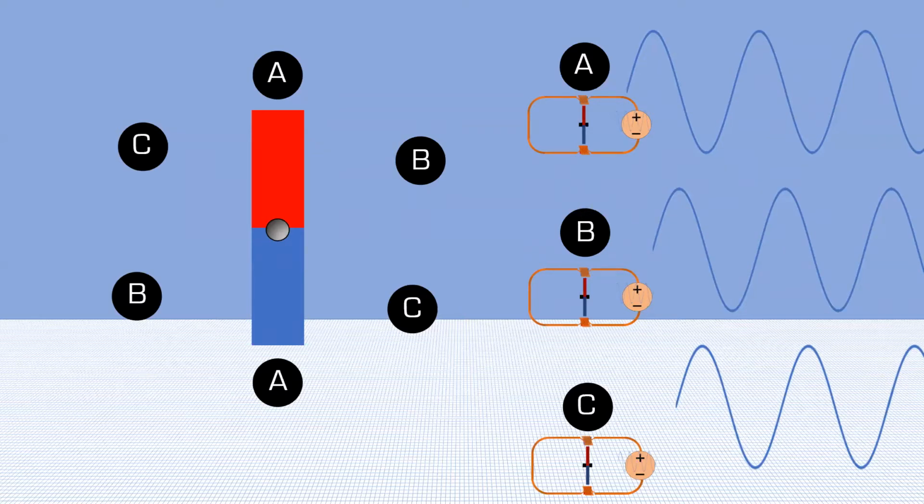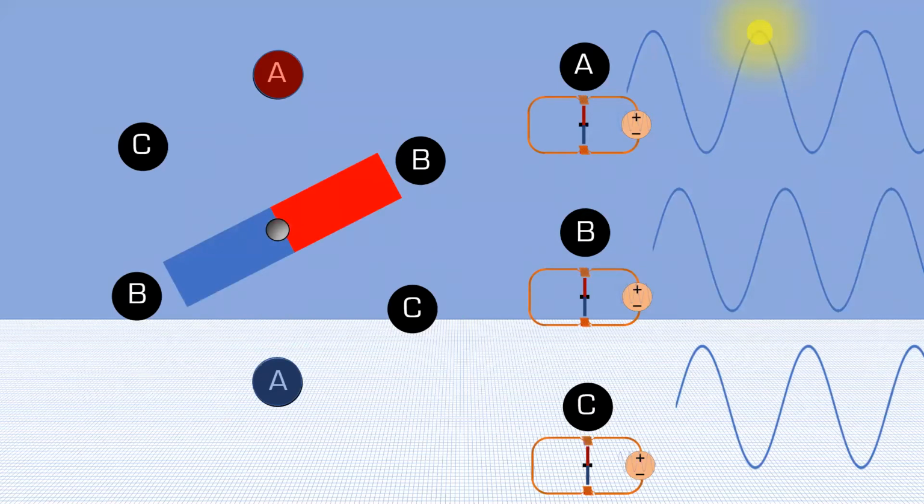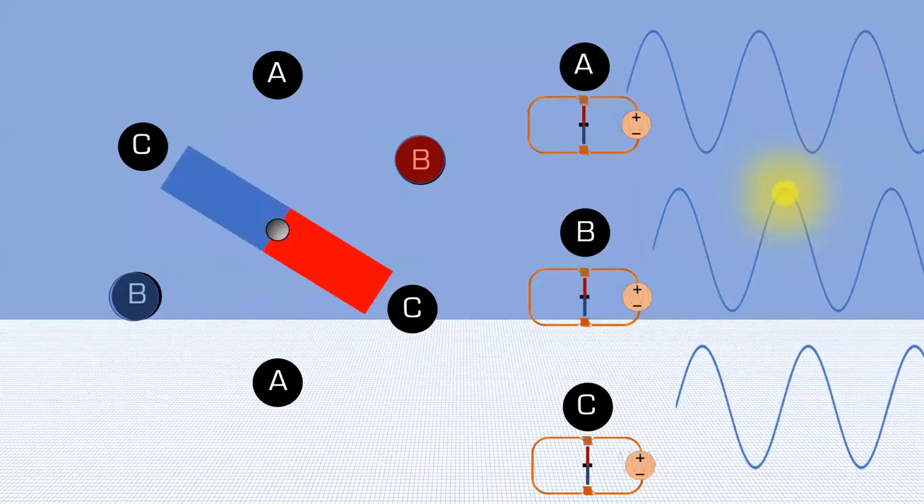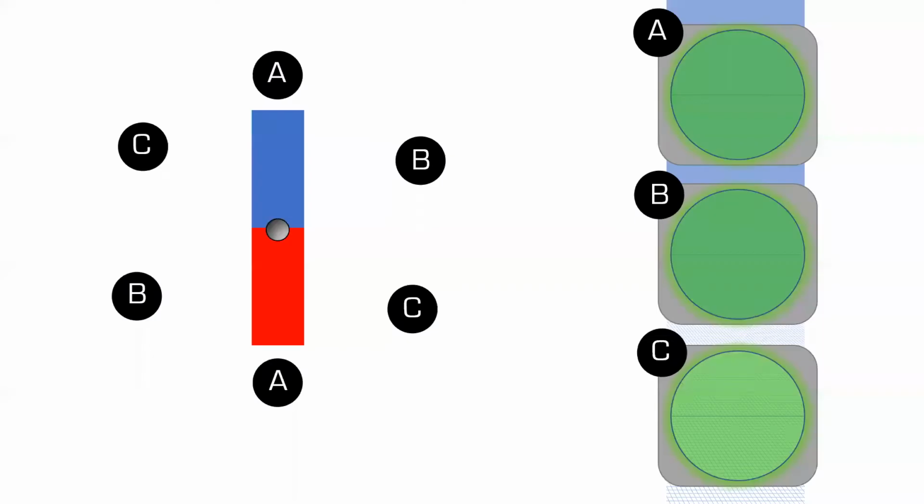So what we get is, when we are at the peak of our A phase, we get those magnets at the A and the B the strongest, and they are going to repel the inner rotor. Then as it comes around, the B phase becomes the largest current, and therefore the B magnets become the strongest, and it repels the rotor once again. And finally, this poor rotor doesn't know what to do. It's chasing its tail, and it starts the rotation process.